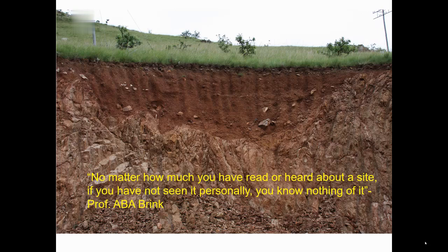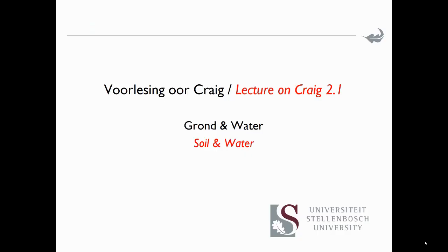So if you dig a test pit on this site in the middle of the channel, you will think that you have a deep soil profile. But if you dig it on either the left or right edge, you will think you have a shallow soil profile. But looking at things like this in road cuttings, you will already have the idea that you may have areas of deep soil and areas of shallow soil, and you can prepare for it in your investigation as well as your site development. As I said, we're going to look at the interaction between soil and water.